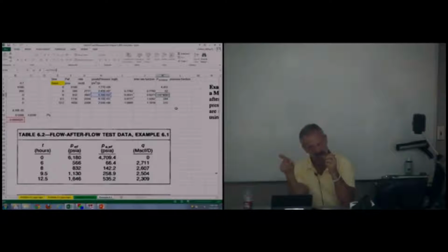I use the viscosity given rather than the one I calculated. But that relative error of 7% is why I can't match their other numbers, because remember, viscosity is built into my pseudo pressure calculation. I don't use the textbook's viscosity correlation. I use the one that comes in that package because it's consistent.